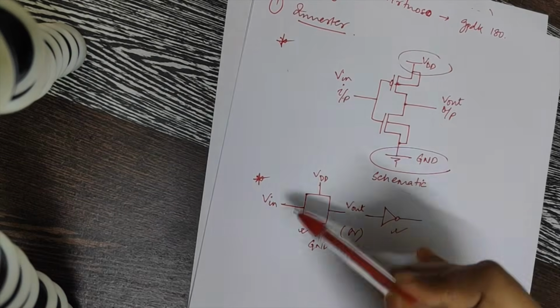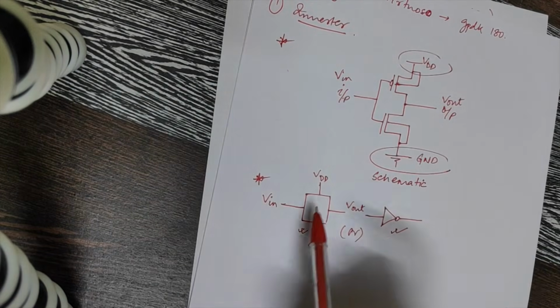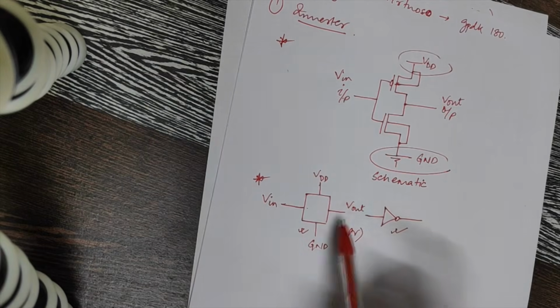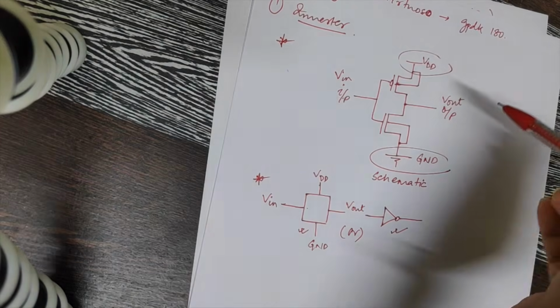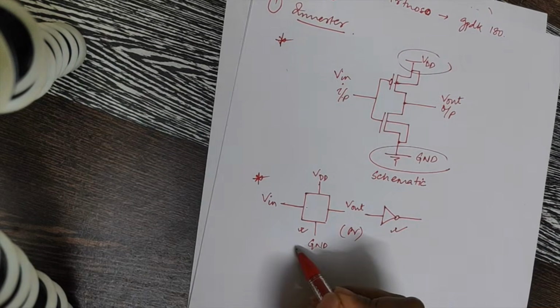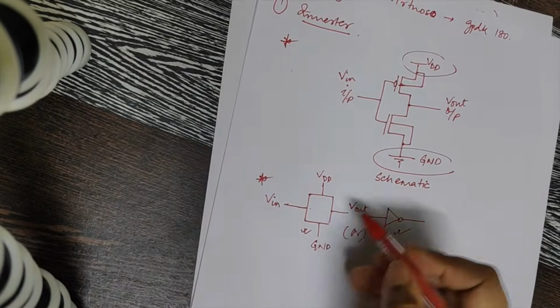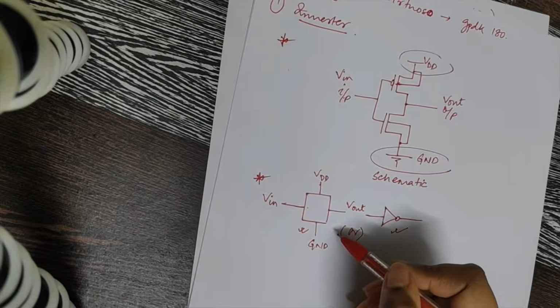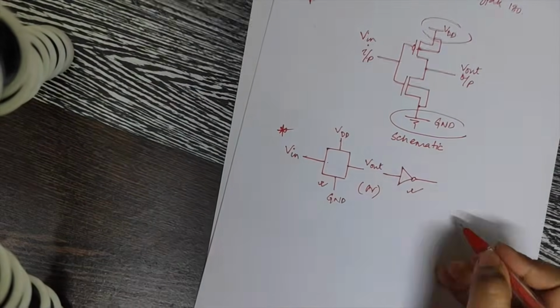There is no connection made. It is just a structure, the body and the pins in the schematic. The number of pins you add in your schematic, that many pins will be present in your symbol also. That has to be maintained. If it misses out, there will be an error.